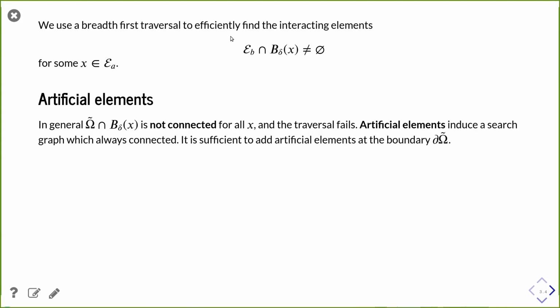That's very nice because this avoids touching all pairs of elements to construct neighborhood lists. Neighborhood lists are not necessary if you have a mesh. That's somehow the advantage of the mesh. A neighborhood list is, of course, expensive in the sense that it costs you maybe as much space as the stiffness matrix or something comparable. So we don't need that at all if you have a mesh, because the information is already there.